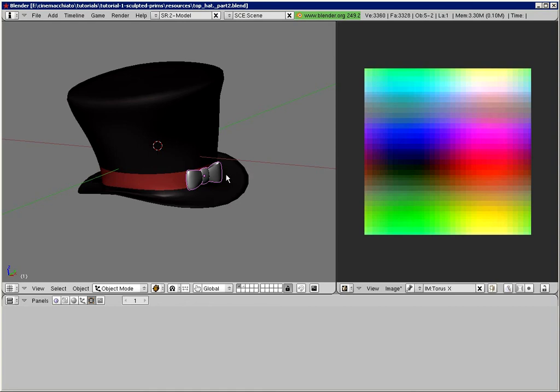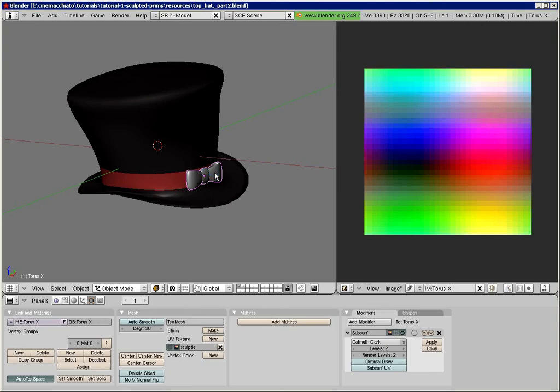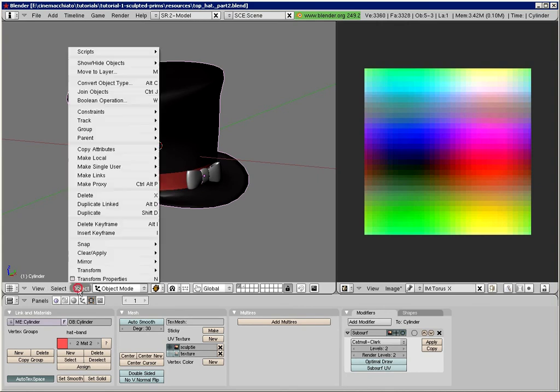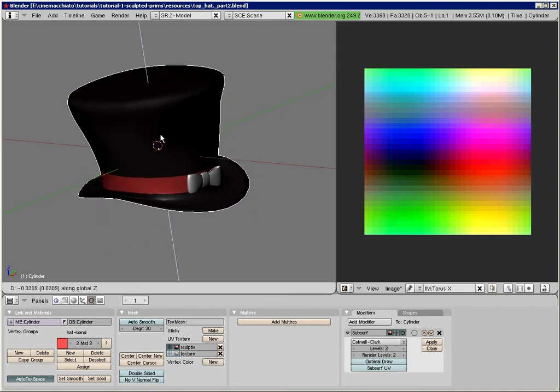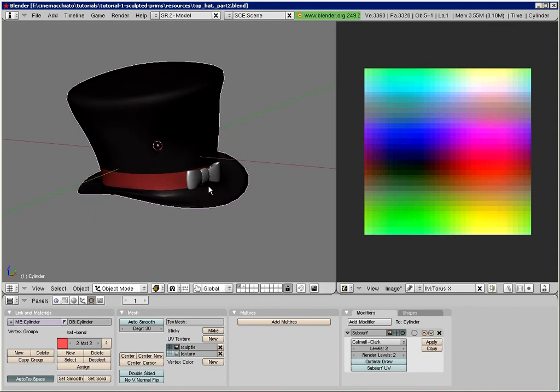First, go to Object Mode. Then select all your objects by holding down the Shift key and then right-click them one by one. Now go to Object, Parent, Make Parent. This makes the last selected object the parent of the others. If you select only this parent object, then all its children will follow any subsequent transformation.